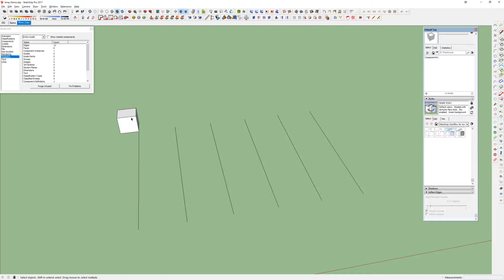Now, similarly, if I grab this and I use this for brackets, adding brackets around a house, I'll grab this, go all the way to the end. So I can say this is my A and my Z location. So this is moving 50 feet. And then I can come back and say, you know what? I want to space 5 evenly throughout. So now instead of hitting X, I'm going to type 5 and then slash, like I'm dividing, hitting enter, and you can see that's now evenly spacing them between the two.